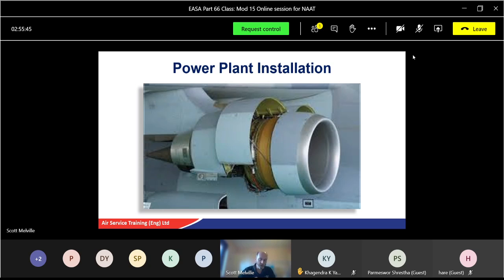What do we call the range when the power lever is brought back through a mechanical stop at idle and goes back the way? Where it goes from flight fine to ground fine and then into, what was the name of the range? The power lever, you're at maximum, you're at idle, and then you're at flight fine, ground fine, and you put it through a gate. What was the name of the range called? It's beta range. So we're in thrust reverse, yeah? Thrust reverse range, good.